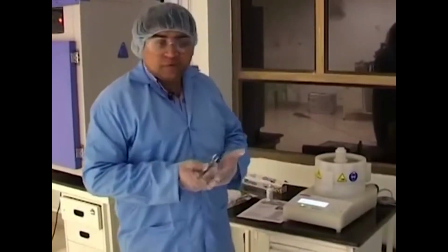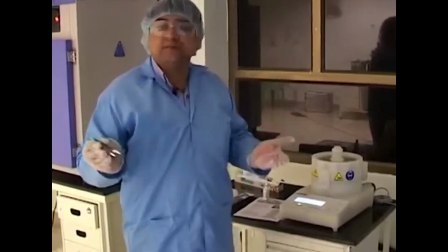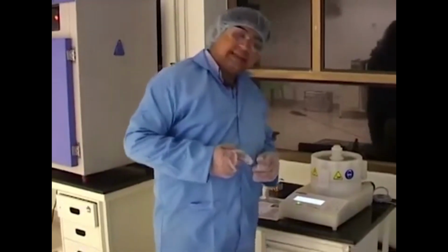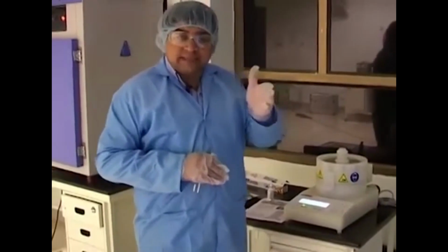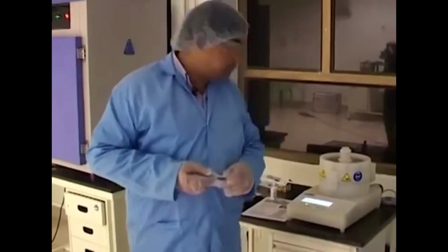We have not cured, and before the curing the film is tacky, and if you have any stresses or any impact on the film, it is going to create a huge difference and make the film not behave properly. Also, we need to assert one basic fact, that the table that we are using for keeping or aligning our hot plate should be perfectly parallel to the ground, because otherwise there may be a possibility of the resist running to one side, thus creating a thicker film at one end, which is highly undesirable, because we want uniformity in the film thickness, which also determines the sizes and nature of our structures and features.